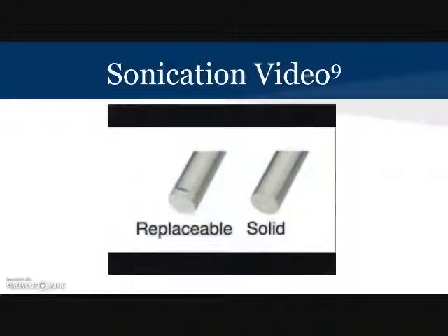So what type of tip should you use? If you're working with an aqueous sample, then you should consider using a replaceable tip. Replaceable tip probes have threaded ends, and when the tip is worn out, it can be unscrewed and replaced.